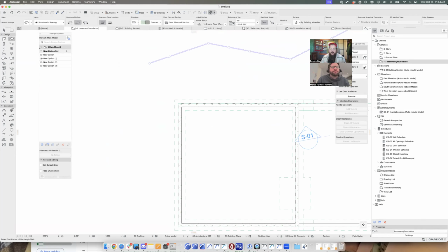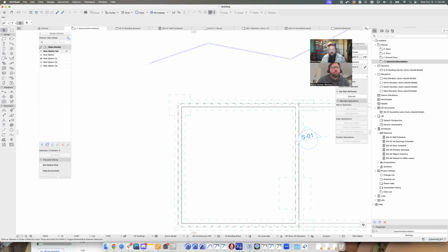Yeah, so let's say I've got a 2x2. Let's just say it's a 4x4 on this corner. So I'm going to start by drawing in just a separate slab. I'm going to say this is X 4 feet, Y 4 feet. I don't even care where it's at. I'm just going to get it in here and line it up. If I know it's going to be centered, I need to be whatever, 1 foot 5-ish inches there to get it centered on that point. But it's going to be the same dimensions as this slab. So I'm going to click the plus option and trace it out. And then I can delete the original slab that I used to trace it out.